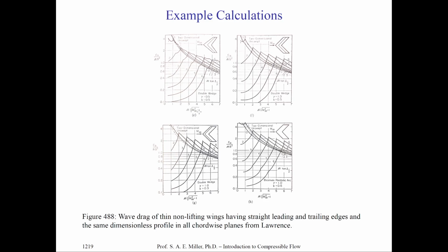You can see particular curves for two-dimensional unswept wings up here, and various sweep angles of wings for double wedges with different shapes of where the diamond is placed, indicated by the line in the upper right corner of each figure. Let's trace across lines at different particular Mach numbers. You can see indeed with varying aspect ratio and beta parameter how the drag increases and falls off almost at an asymptotic line, which can be drawn through each of the particular curves.